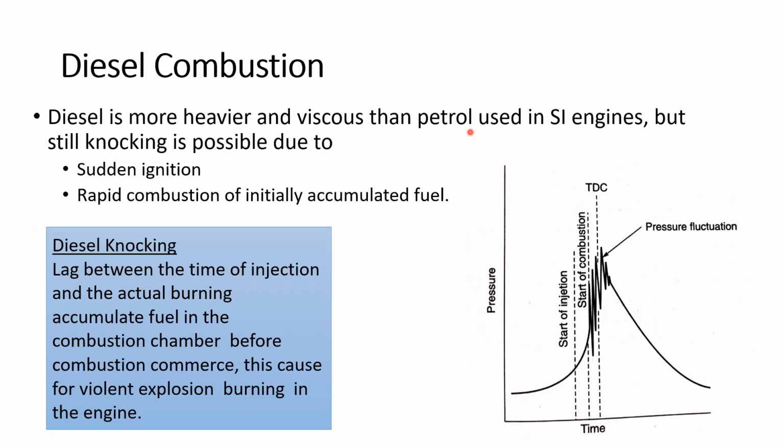To fix this, for diesel engines, similar to the petrol engines, there's a rating. It's known as the cetane number, right? The cetane number is higher for fuels that need to be used in higher compression diesel engines. Mostly for modern engines, you might have heard of super diesel, which actually has a higher cetane value. The reason being, these diesel engines were designed to run at the optimum level in order to save fuel and to be as efficient as possible.